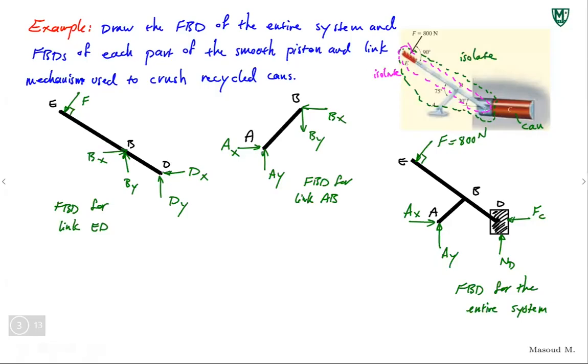Right? Yes, Richard, that's where I was going. So this is a 2-force member. AB is a 2-force member. It's like a truss member. So if you figured that out from the beginning, which you could, this would be AB. So this would be force A, this would be force B. So you can find A and B, and you're going to eliminate some unknowns.